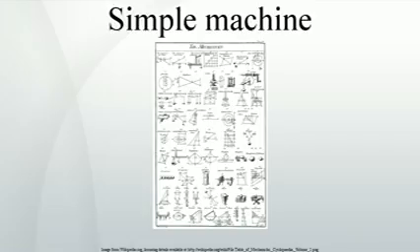Compound machine. A compound machine is a machine formed from a set of simple machines connected in series with the output force of one providing the input force to the next. For example, a bench vise consists of a lever, the vise's handle, in series with a screw, and a simple gear train consists of a number of gears, wheels and axles, connected in series. The mechanical advantage of a compound machine is the ratio of the output force exerted by the last machine in the series divided by the input force applied to the first machine. Because the output force of each machine is the input of the next, this mechanical advantage is also given by the product of the individual mechanical advantages. Thus, the mechanical advantage of the compound machine is equal to the product of the mechanical advantages of the series of simple machines that form it.